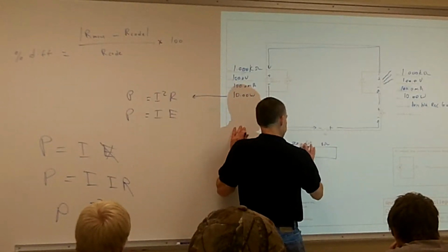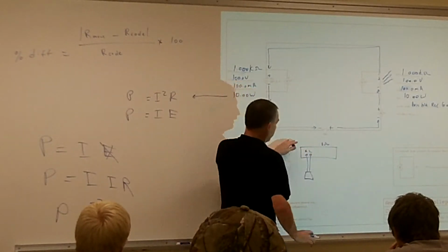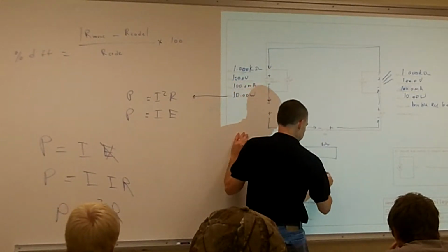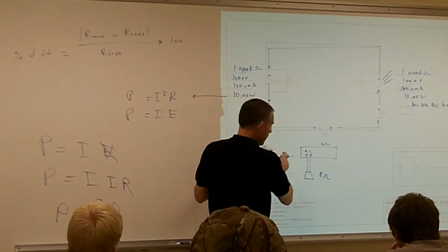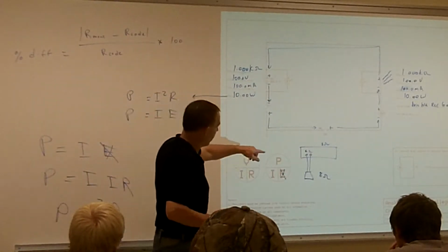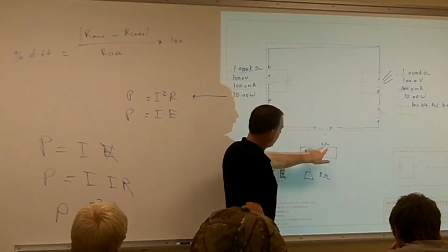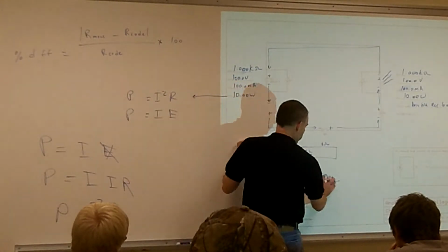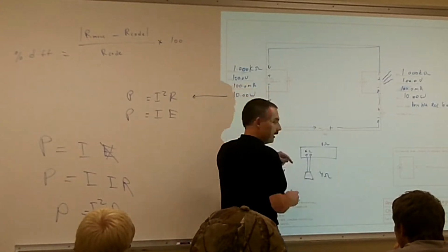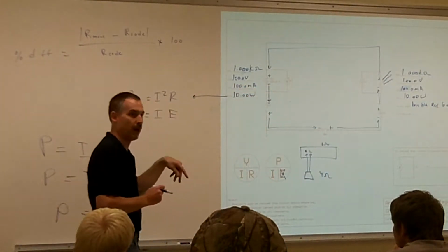Well, if I have an 8 ohm system, I want to make sure I have an 8 ohm speaker. I'm going to get my maximum amount of power out of that speaker when it matches up with my amplifier. If I put in a 4 ohm, you'd think that I get more current, I get more power, but I don't. I lose my power.